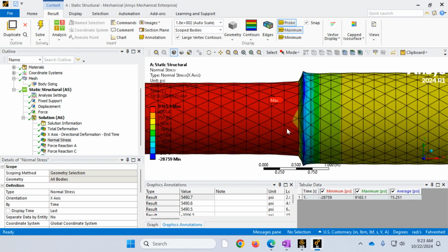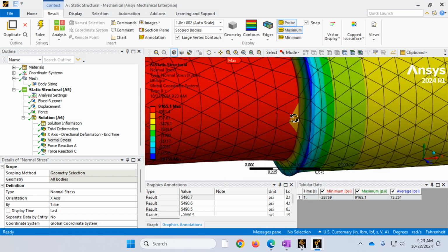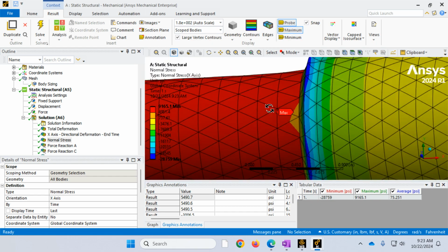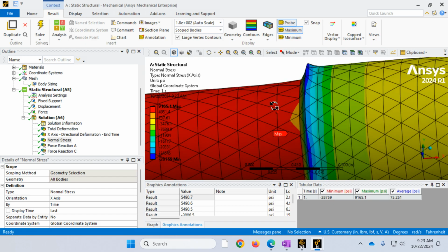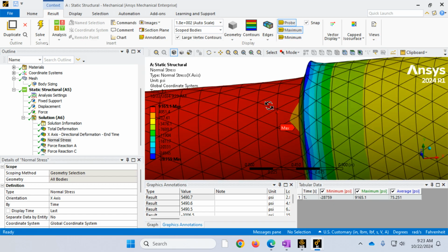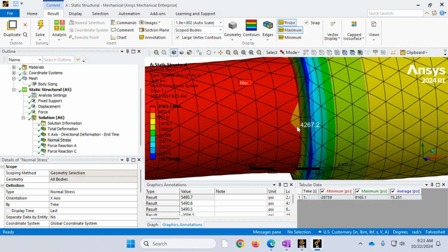And it is pointing at a point that has a very high stress. And you will see this is close to the discontinuity. So that very elevated stress is somewhere where there is a change in the diameter. And indeed, the stress varies within the elements here, and this is not what I really expect to see.